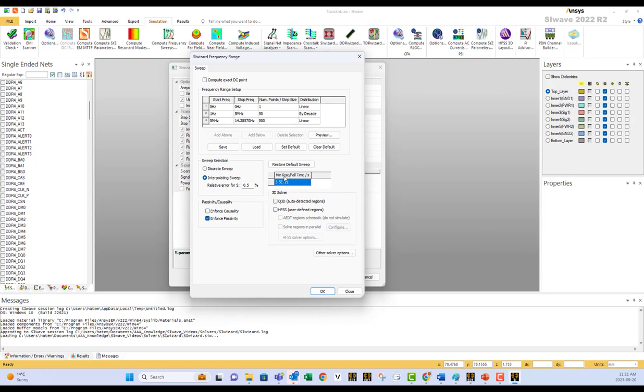Notice here the rising time. This rising time number is connected to the highest frequency in your setup. So if you change this number, if I, for example, say instead of 3.5, I say 4.0, immediately the number will change here. You will notice that the number changed to 12.5. In our case, the rising time was 35 picosecond, and consequently, we need to simulate our system minimum to 14.28. You can go beyond that if you want.